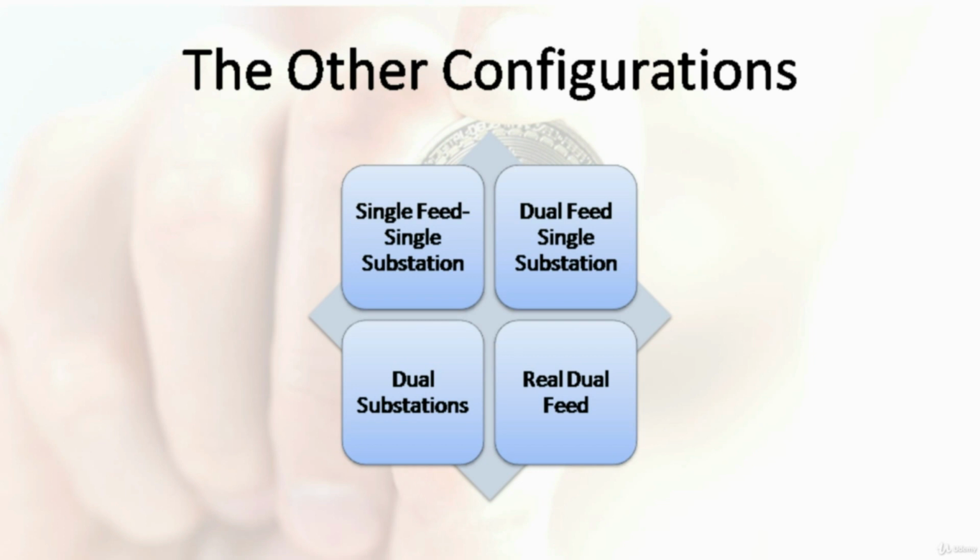This in turn eliminates the risk of a single line breakdown triggering a sustained outage by providing two distinct feeds. With the use of only one substation as the power source, this configuration nevertheless still holds a high probability of extended power outages. Not only that, the feed downstream of the switch into your facility may still be susceptible to a single point of failure.